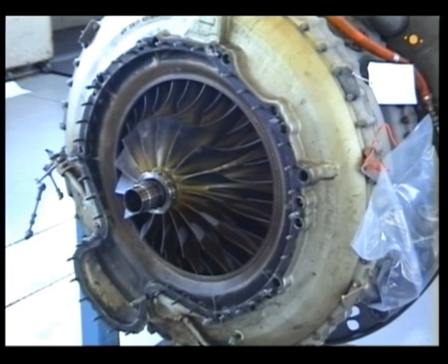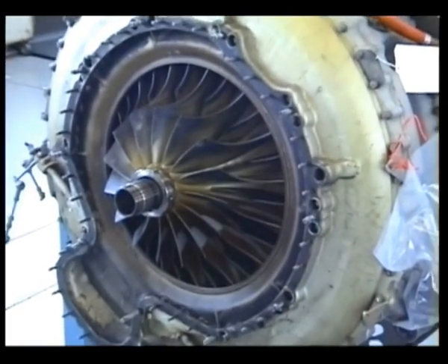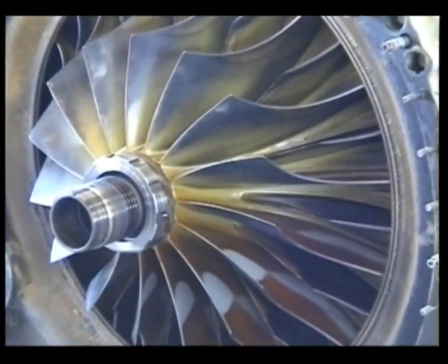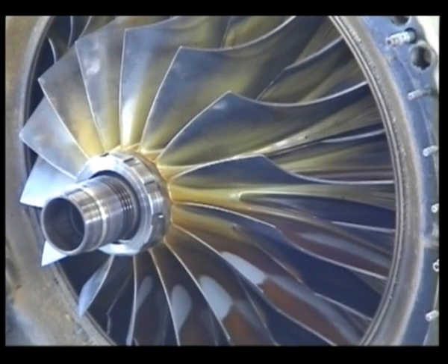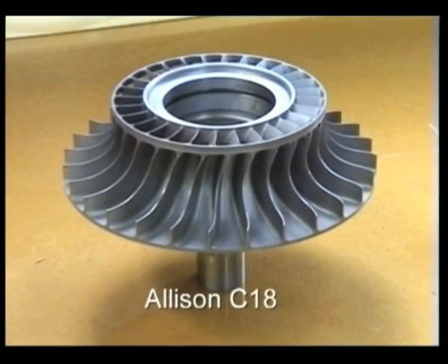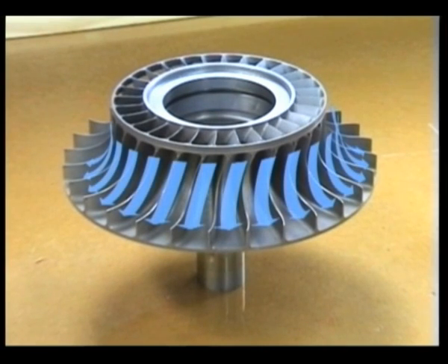The main component of a centrifugal compressor is an impeller rotated at high speed by the turbine. Impellers may be manufactured from aluminium alloy, steel alloys, or titanium. Centrifugal action causes the air to flow radially outwards between the vanes. At the same time, the impeller rotation causes tangential flow.